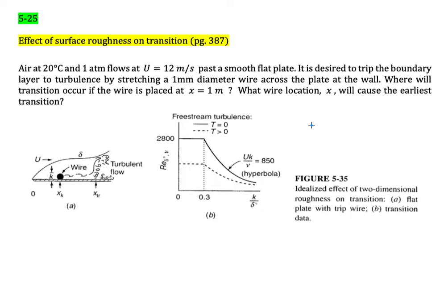The most common one is the surface roughness, meaning the quality of the surface. The surface roughness in this term can be divided into two. One is the natural surface roughness, because no matter how hard you polish a surface, it will still have hills and valleys in its topography. So the surface will more or less influence the flow.